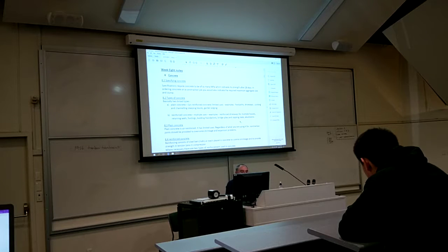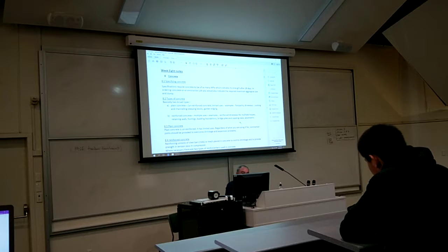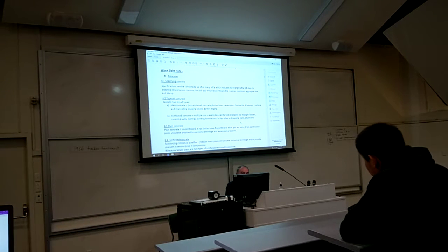So, when we specify concrete, we specify it in terms of its strength after 28 days. Not a month, 28 days. That's really important, and it should be one of your first notes on your concrete drawing. And it's also one of the questions in my test.